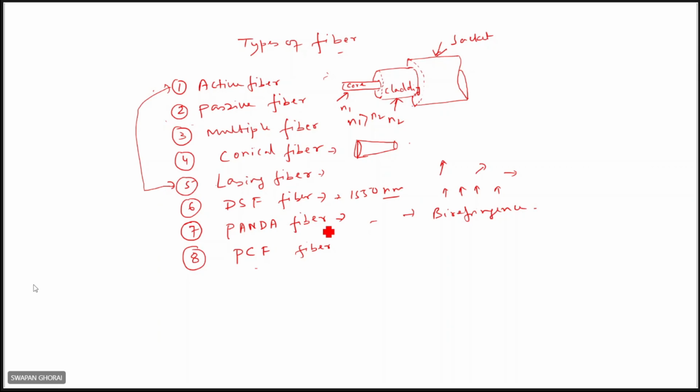Here the theory will be totally different. You have seen a single clad and single core, but here it can be multiple clad, right? And instead of a high refractive index, there can be air holes, where energy can be well trapped. These holes can be air-filled, or filled with some other liquid or gas. Accordingly, there are two types of fibers. Holey fibers, and the photonic band gap fibers. Those fibers are there.